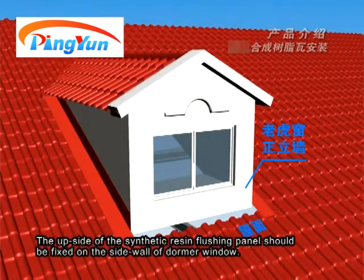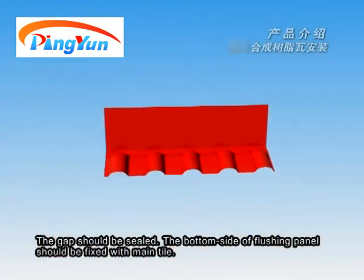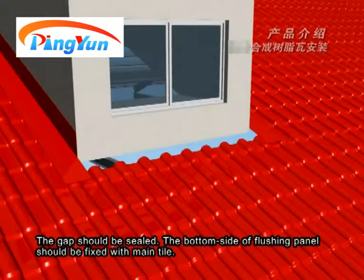Our company's matched synthetic resin flushing panel can be used for the waterproof process. The upside of the synthetic resin flushing panel should be fixed on the side wall of the dormer window. The gap should be sealed. The bottom side of the flushing panel should be fixed with main tile.